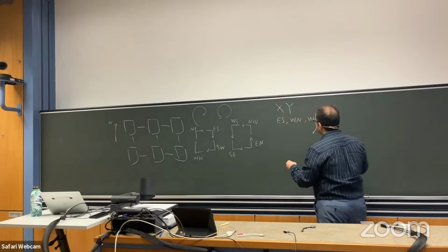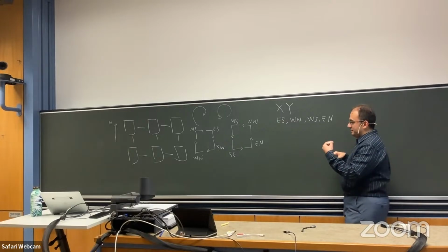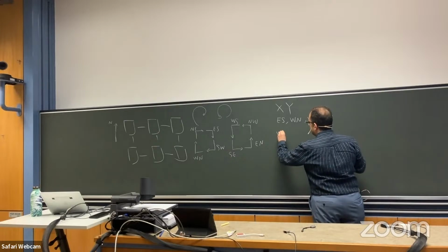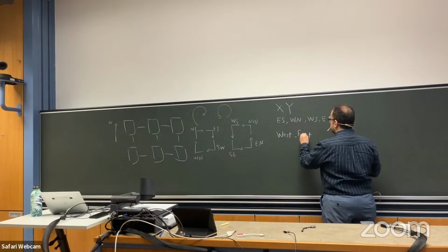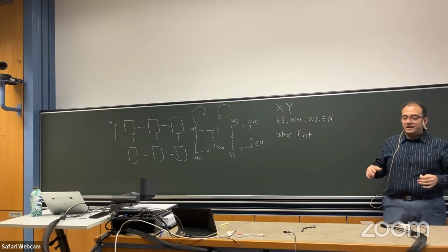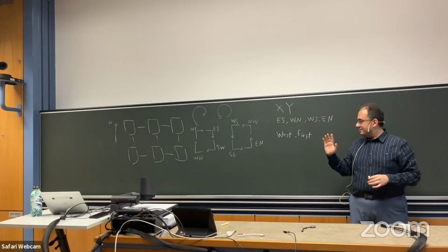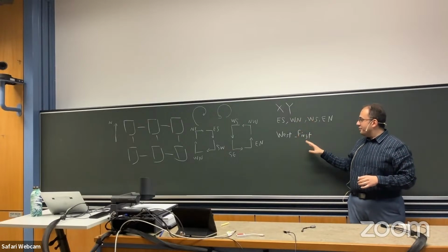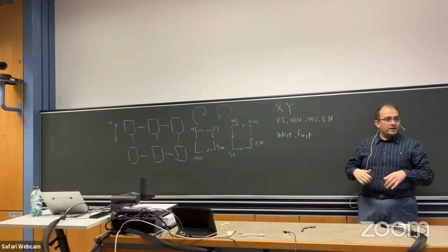But one of the famous routing algorithms that is deadlock free and also considered partially adaptive is west-first. What it says is that if you want to go west, you need to go west first, and then you can go north and south. Essentially, if you want to go west, you need to follow XY, and if you want to go east, you can be adaptive.